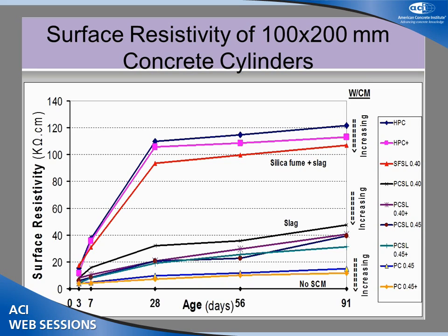We have sort of high-performance concretes with silica fume and slag, and the top 3 curves are there, but the difference between the 3 curves there are different water cement ratios. If water gets added on site, you can see the resistivity drop as the water is added. And we see the same thing with some straight slag mixes, and down at the bottom with some Portland cement mixes. So it is sensitive to small changes in water cement ratio, and it is very sensitive to different cementing materials, because supplementary materials typically increase the tortuosity of the pore structure so that you get higher resistivities.